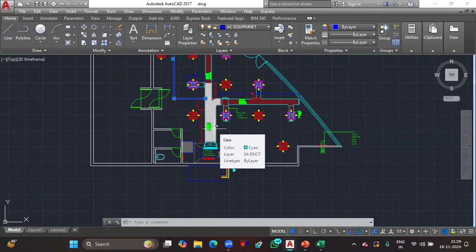It has to be pressure drop, head loss. So what should be the unit of this pressure drop or head loss? It's quite simple. While designing our duct, we learned something called the equal friction method. You remember? In that step, I explained that the pressure drop or frictional loss we maintain inside our duct should be 0.1 inch of water column per 100 feet of duct.